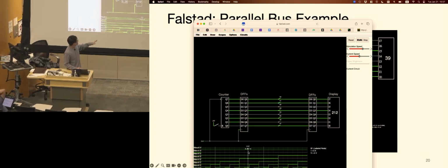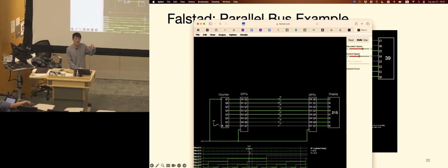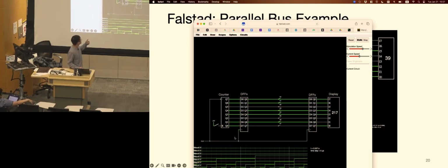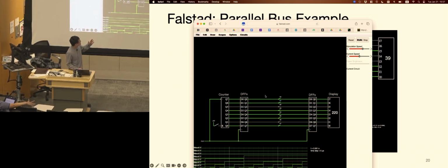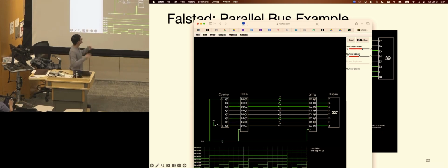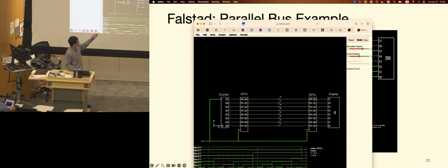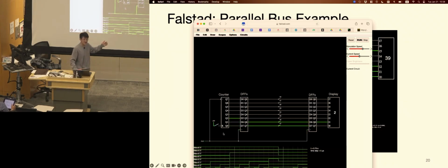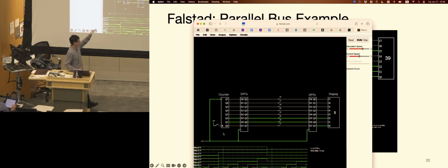So basically, what it does is it increases the value by one every cycle, and just keeps on going. Every time the clock edge goes positive, all those values get updated along all the flip-flops. Usually they have a reset, so if I reset it, nothing happens, and if I disable the reset, it goes back to the calculation, doing the exact same thing over again, counting up by one every time.